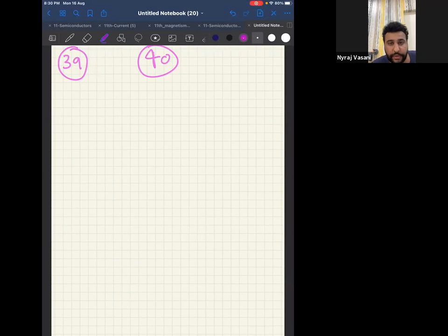I told you that the combination is not in series because there is a node in between. Last class also we have done similar. Now tell me the answer for 40. Correct. Sharvari correct. Sumitra correct. Devansh, Malhar, Sakshi, Yash, Riya, Aniket correct. Answer is B. Answer for the 40th question will be B, correct? Because I know that they are not in series. If not in series, they will have to be in parallel. And the parallel combination will be 3C, that is C plus C plus C, which will be 3C. Therefore, 40th one answer is B, which is clear.